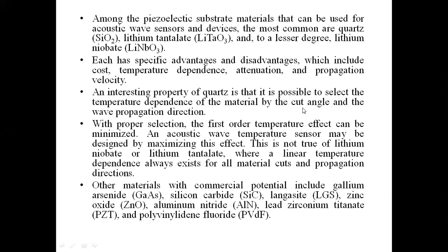Attenuation and propagation velocity. An interesting property of quartz is that it is possible to select the temperature dependence of the material by the cut angle and the wave propagation direction. With proper selection, the first order temperature effect can be minimized. Acoustic wave temperature sensors may be designed by maximizing this effect. This is not true of lithium niobate or lithium tantalate.